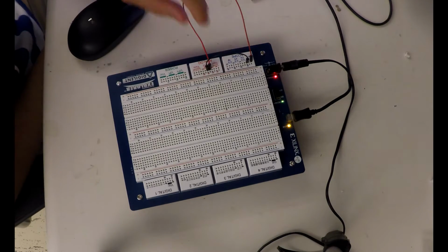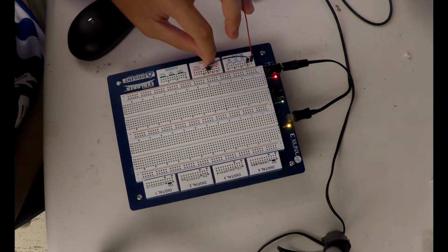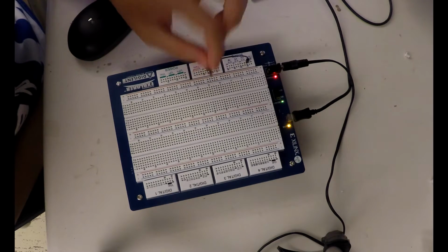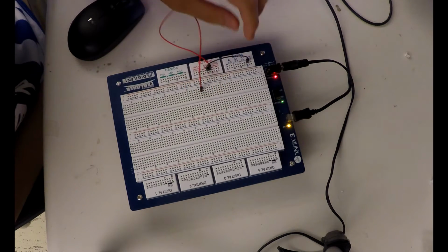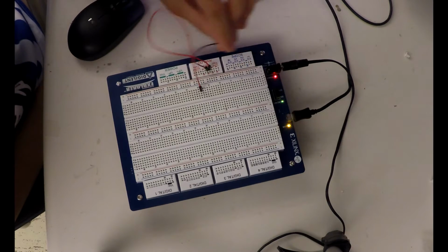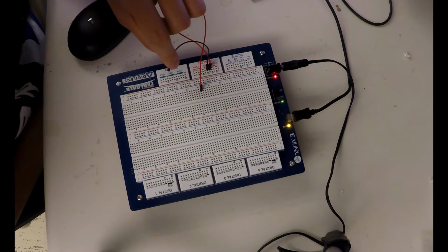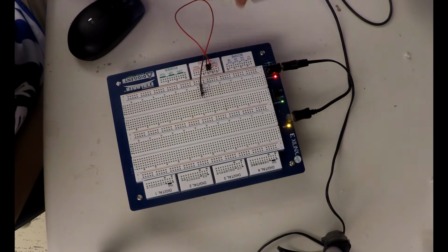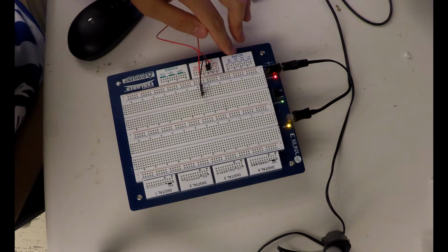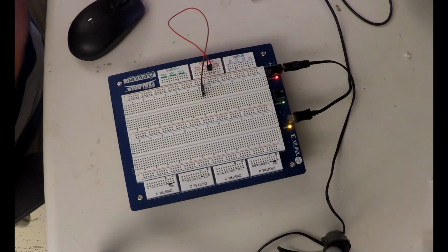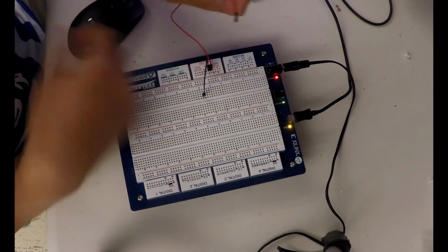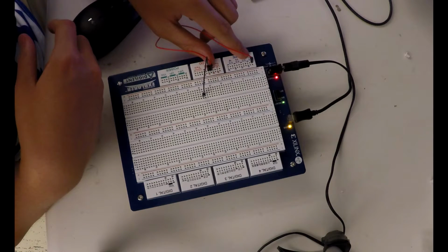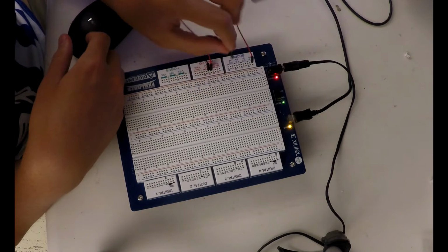On the board, we do have the channel 1. This will generate the voltage to whatever node you desire, place on any arbitrary node, and we do have to ground the AWG, so ground it whatever is appropriate. In order to measure, we do have to use the oscilloscope on the top of the board, so we will have to change the lead. We will be utilizing channel 1. Make sure that you do select the AC portion, and we will have to ground that.